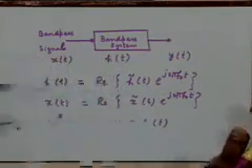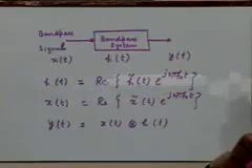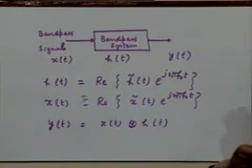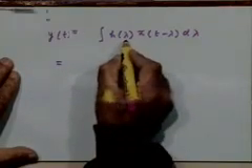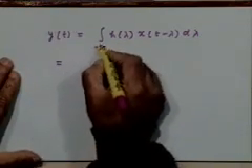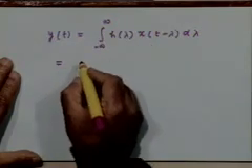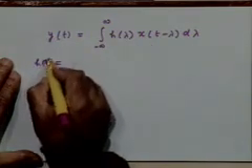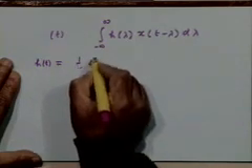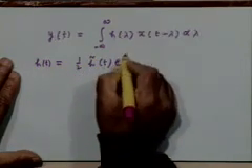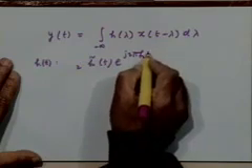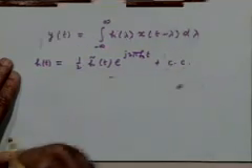The real part of any complex number is the sum of the number and its complex conjugate divided by 2, right? So I could represent h lambda here. Lambda of course is a dummy variable, from minus infinity to infinity. I could write h of t as half of h tilde t e to the power j 2 pi f naught t plus its complex conjugate, right?